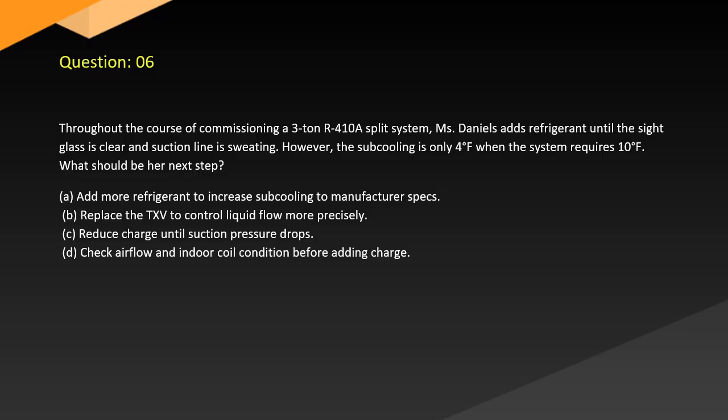Question 6. Throughout the course of commissioning a 3-ton R-410A split system, Daniel adds refrigerant until the sight glass is clear and the suction line is sweating. However, the subcooling is only 4°F when the system requires 10°F. What should be his next step?